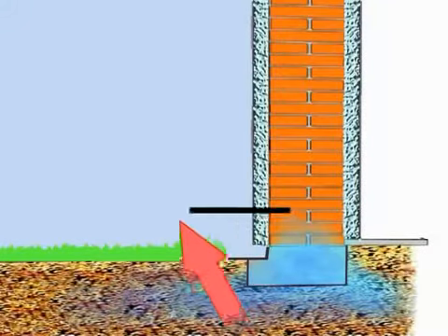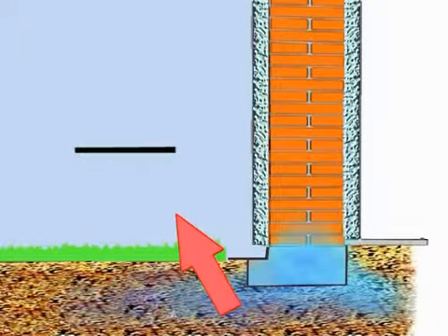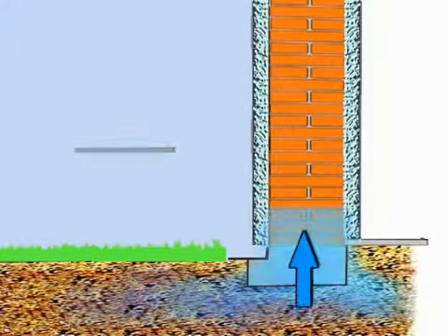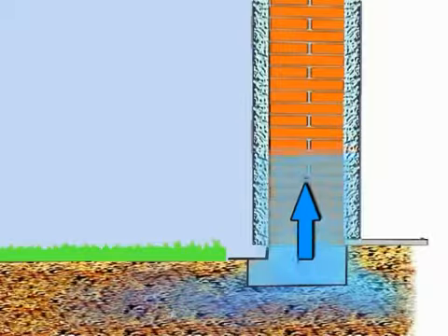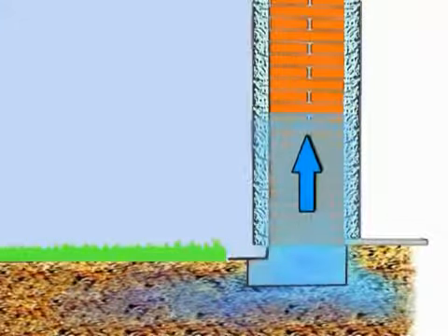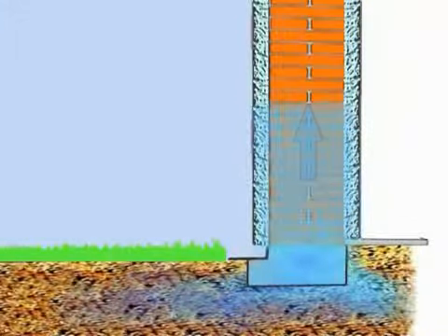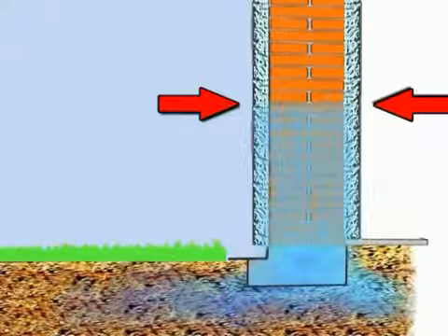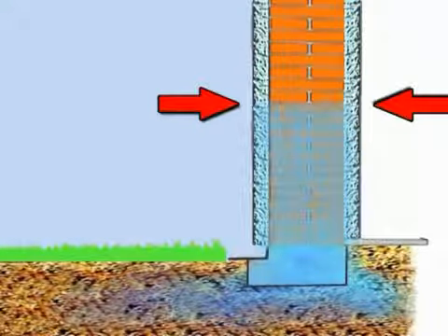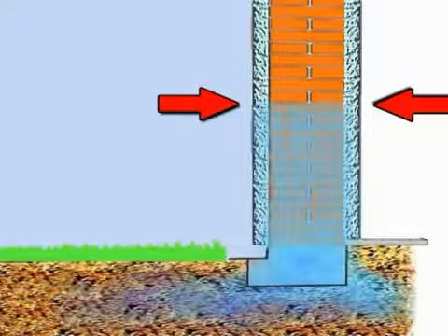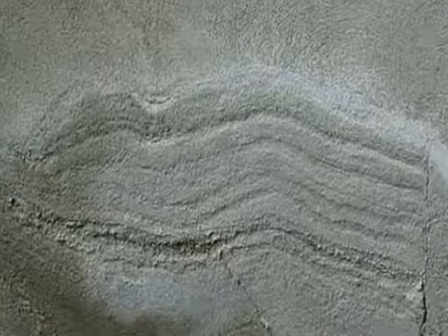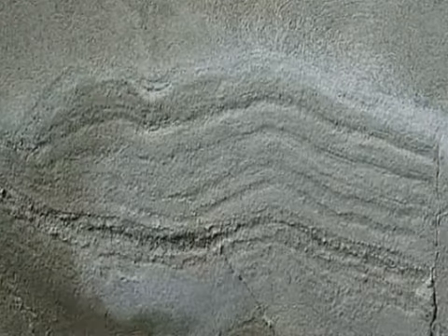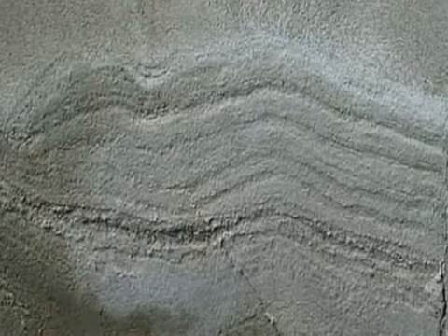In old masonry that lacks a horizontal moisture barrier or where it is partly rotten, ground moisture rises into the masonry. Ground moisture in the capillaries of masonry rises to a point where it oozes out as water vapor at the so-called evaporation zone. This results in the capillary head in masonry, which grows a little every year. It may be manifested as annual rings caused by different degrees of salt efflorescence.